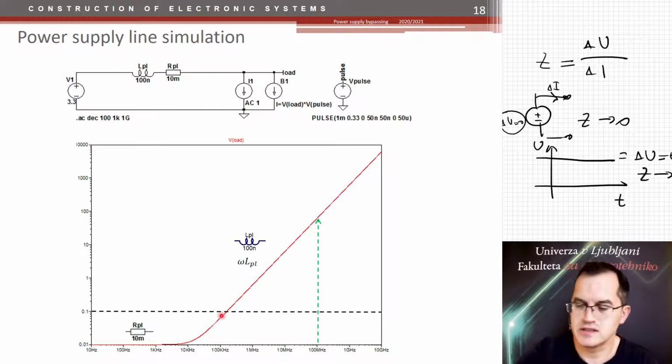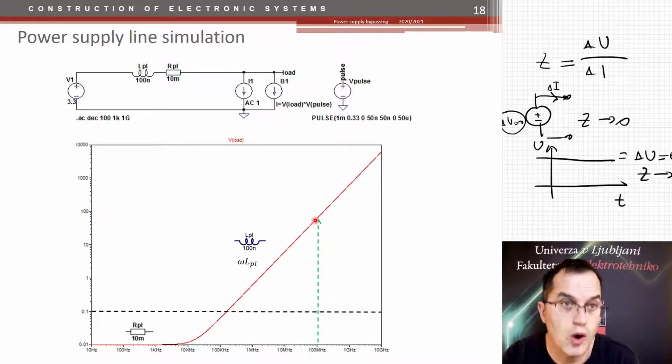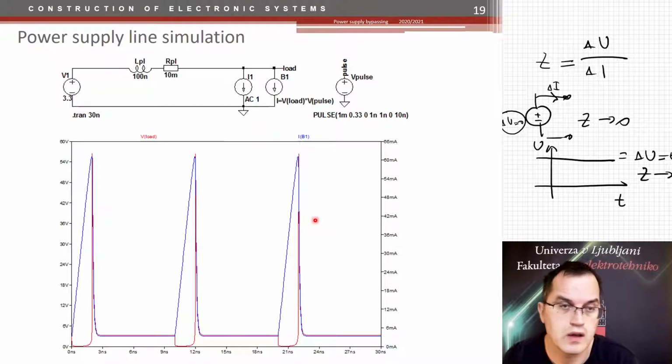And if I go into simulations now, you would see that this impedance at 100 megahertz, which instead of being 100 milliohms, is in the range of 100 ohms, would be causing a lot of problems. Taking 1 amp current from the power supply would actually not even be possible. So actually I'm making it here a little bit harder. I make it a resistive load.